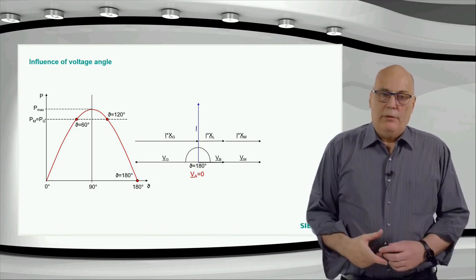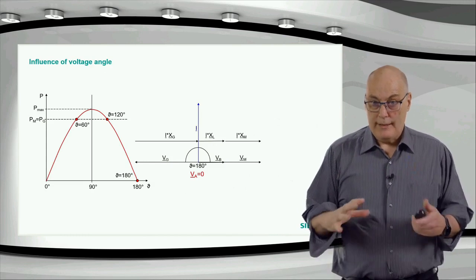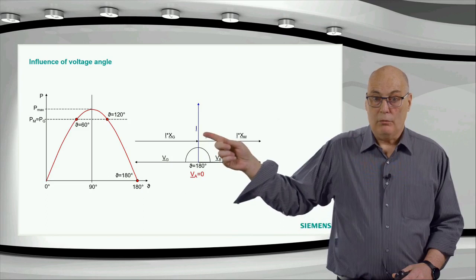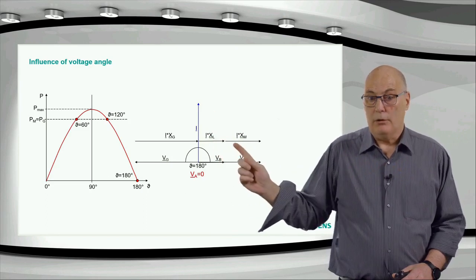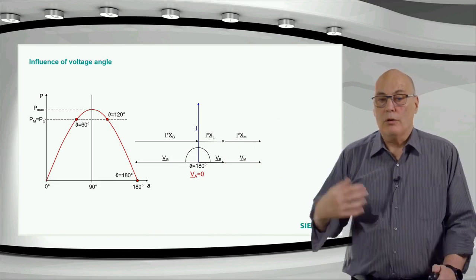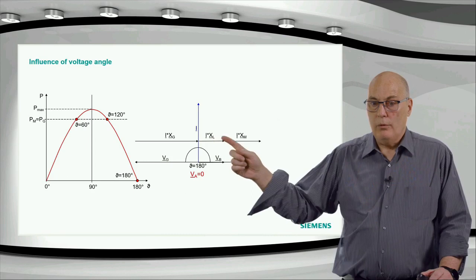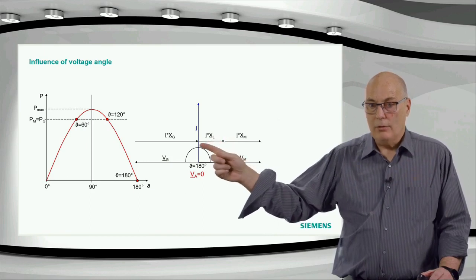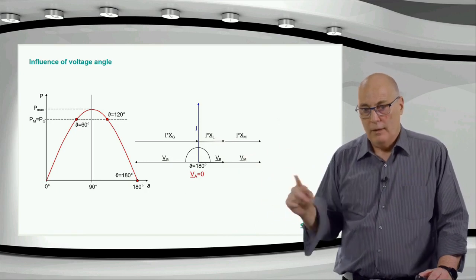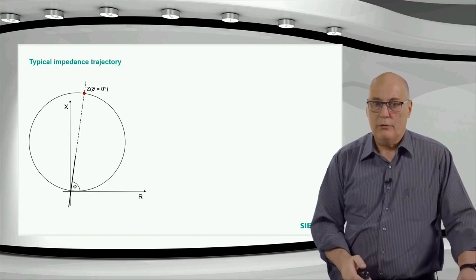Okay, these diagrams are very interesting, but remember we are looking at the distance protection, and we're used to seeing impedances. These are voltages, real voltage. Current was also shown, but the I times Z drops are also voltages. To transfer these voltages into the impedance plane, you simply divide all the I times X voltage drops here by the current, and then you get reactance. So try and take this diagram that we have here now, and I'm going to transfer it over here